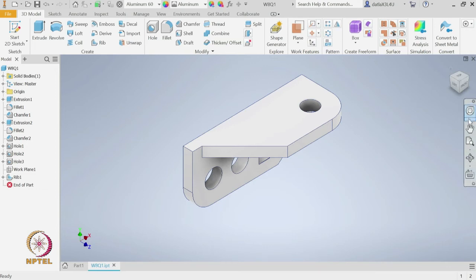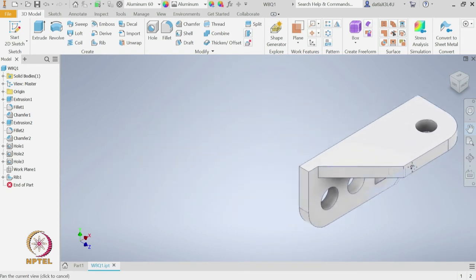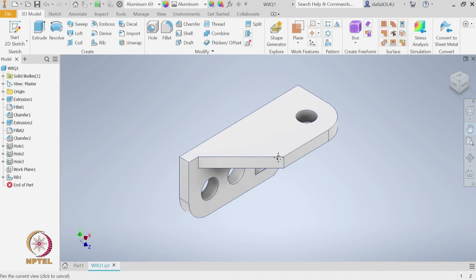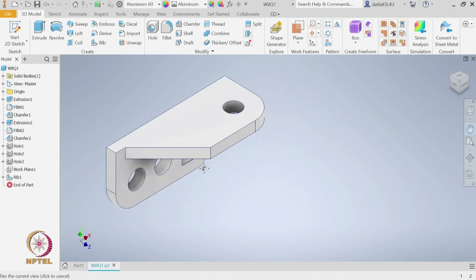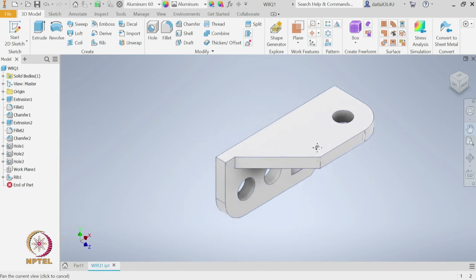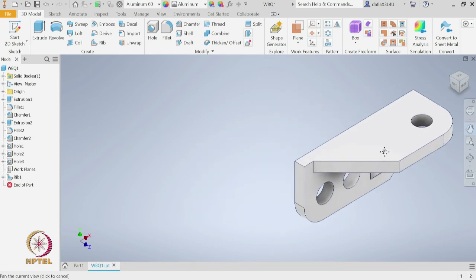Okay. So, let us start with pan. So, pan, after I click this pan button, I need to come to the drawing area and just click and drag. So, click and hold. So, once you release the hold, that will be your final location. So, let me repeat, first click, then hold and move it and then leave the click button.